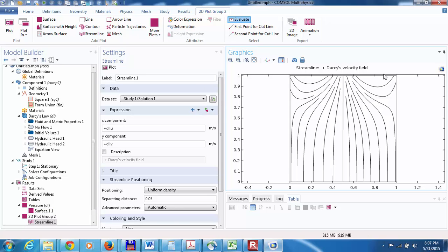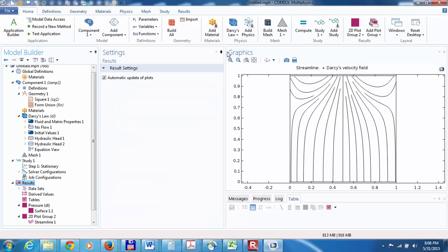As I mentioned, if we calculate the fluxes across this boundary and across the bottom boundary using just the conventional Darcy fluxes, we'll find that they're not going to be the same. The net flux across the top boundary will not be equal to the net flux across the bottom. Because of steady state flow, those two fluxes should have the same magnitude. One will be positive, one will be negative. So there would be a mass balance error associated with that. All right, so let's look at that.